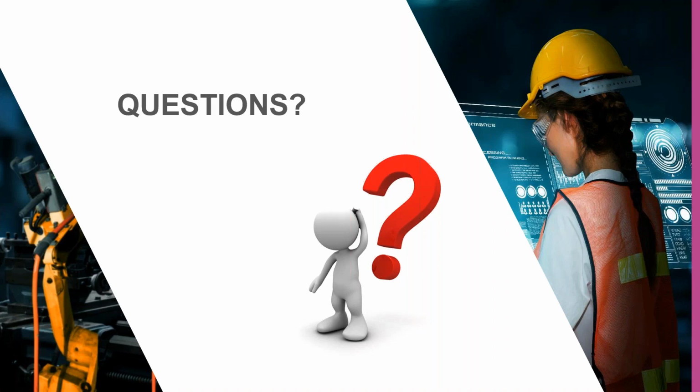But I assume that yes, because this is a feature type within Creo MBD that's specific to Creo, that part file would only be able to be shared with other Creo users. And even though this is not something in the demo, what you can share is a PDF. There's a way to export an MBD to a PDF, and that's obviously something that can be shared.